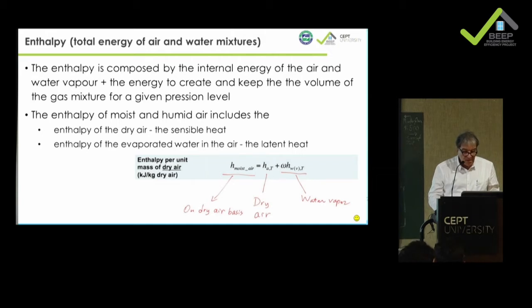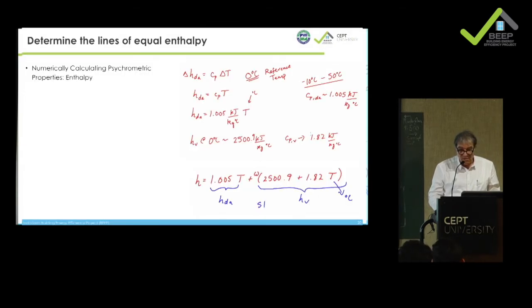So now, there will not be much equation, don't be afraid, but I think it's important just to try to go through how you come to the enthalpy lines, because in the psychrometric diagram that we are going to construct, we will have lines where you have absolute humidity, lines where you have temperature, and lines which are of constant energy, which are across the diagram. And I think it's important to have these three basic understandings of the lines.